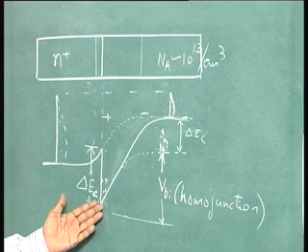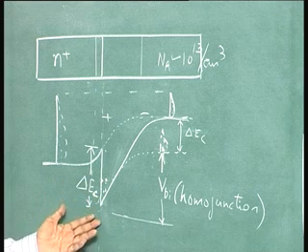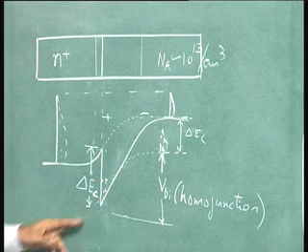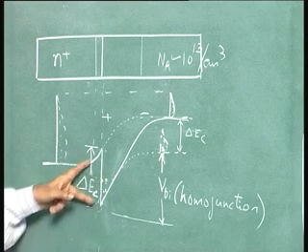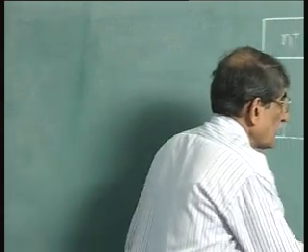Band bending may be there. If I have a homojunction, there also band bending is there, but there are no electrons left there because they will roll down. Here they will remain because that notch is there. In the case of a MOSFET also, if you recall, when the inversion takes place, the electrons remain there in the inversion layer. Why? There is a notch. If you recall that,